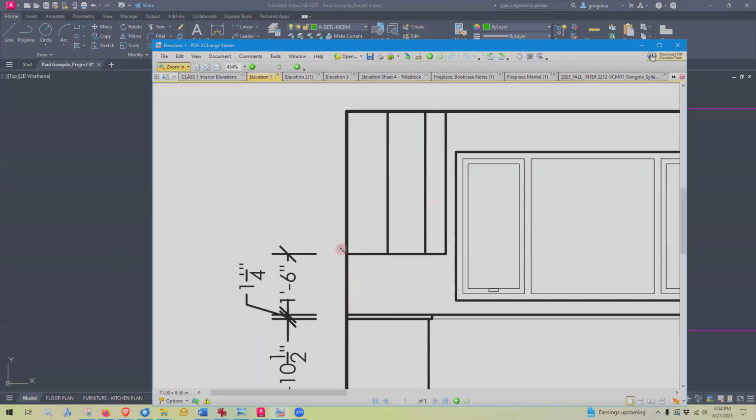And then wall cabinets almost always are a foot deep, 12 inches deep. Your kitchen cabinets at home, if you put a tape measure to them, will most probably be 1 foot deep. So I'm going to make this 1 foot deep, and then bring it all the way to the ceiling. If you wanted to stop it a foot below, you could and come back here. But just for this exercise, I'm going to bring it out a foot and then up to the ceiling. Okay.